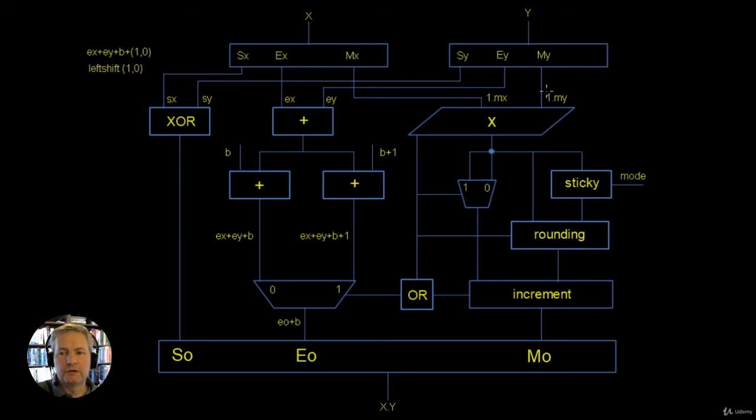So here's the multiplication here, and we're taking the 48th bit of this multiplication, so let's take it down here. Now ignoring this OR gate for the moment, this 48th bit comes in and we use this as a choice. So this 48th bit chooses whether we add a 1 or we add the 0.